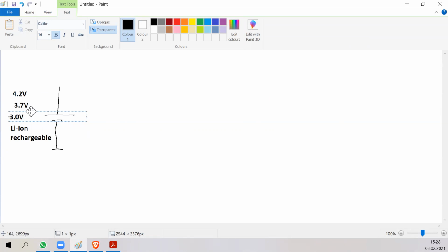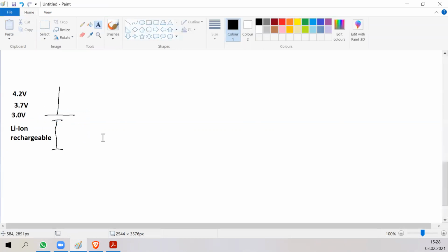It's for its own protection. Your software should switch itself off at something like 3.5, 3.4 volts. That's already too low. But if your microcontroller, for example, hangs and doesn't do it, then batteries have a protection circuit inside, which automatically just switches them off.